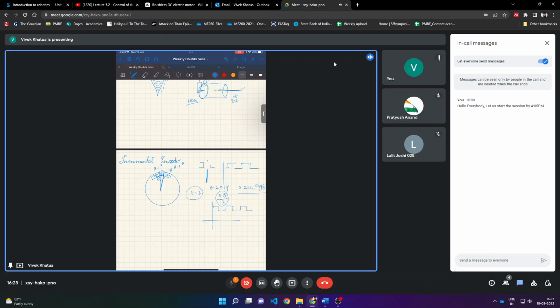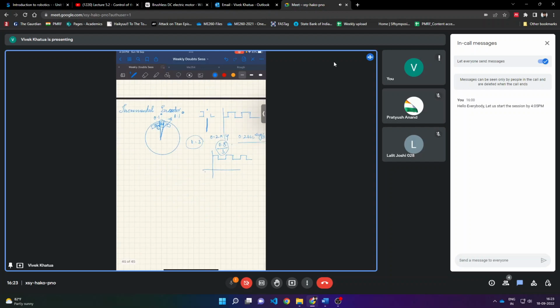This you can convert to radian per second. So now here we would reduce this time interval dt to some frequency that doesn't hamper the electronics attached to this. What I mean is that most of my clock frequency is not occupied in determining my encoder, or there is a specific chip IC that is made to record this value, right? Either way, I can reduce my dt to a very small value.